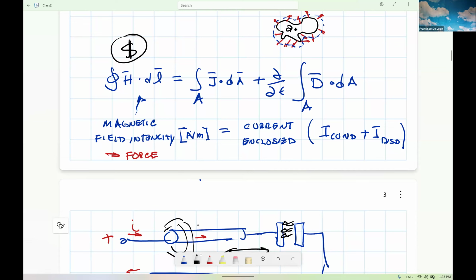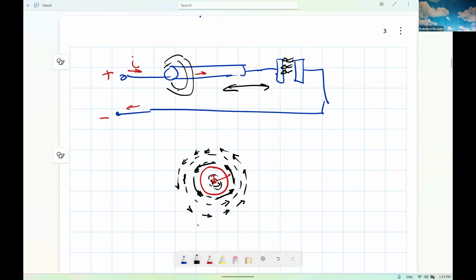I know we are used to seeing equipotentials, mappings, colors, surface plots, and even streamlines. Yeah, we are used to all those things. But the real way is to look at the vectors. If you look at the vectors, it will never tell you a fault. So what is this telling you? This is telling you that around a conductor that is carrying current, there is a force field. And the force is trying to push you to circulate around the conductor, right?